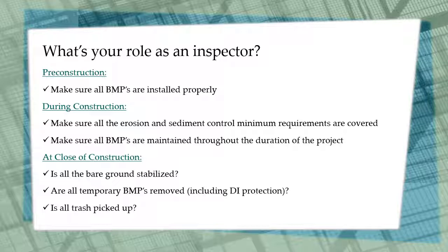Make sure that all the BMPs are maintained throughout the duration of the project. And at the close of construction, check to make sure that all bare ground is stabilized. Make sure that all the temporary BMPs are removed, including the drop inlet protection devices. And make sure that all trash has been picked up around the site.